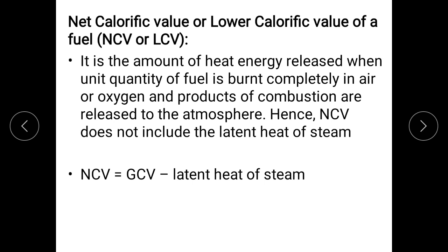So put together, finally if you want to put GCV and NCV in terms of mathematical expressions, then NCV you can write as GCV minus latent heat of steam. From GCV, if you subtract latent heat of steam, you get NCV. To NCV, if you add latent heat of steam, then it is GCV. So GCV is always greater than NCV.